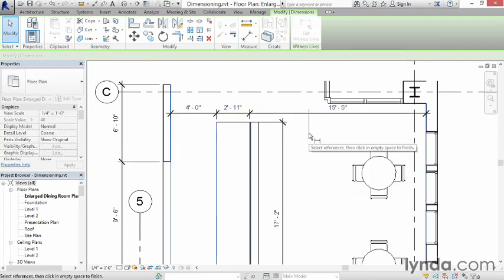All of the existing witness lines that you've already chosen will highlight in blue on the screen, so you can see them there in blue, this one, and so on. And what you notice here is that this one here is actually inside that countertop slightly, so it's not even really in the right place. So what I want to do is, if you click an existing blue witness line, it will remove it. And if you click a new edge, it will add it.